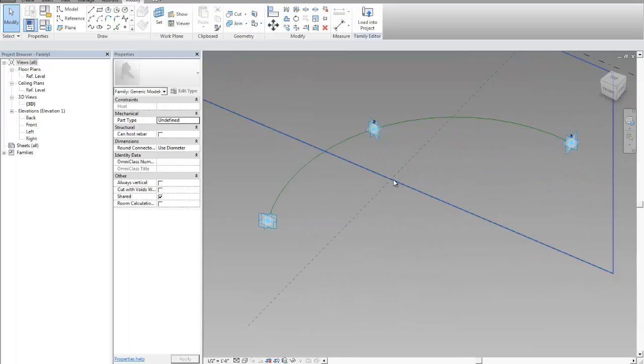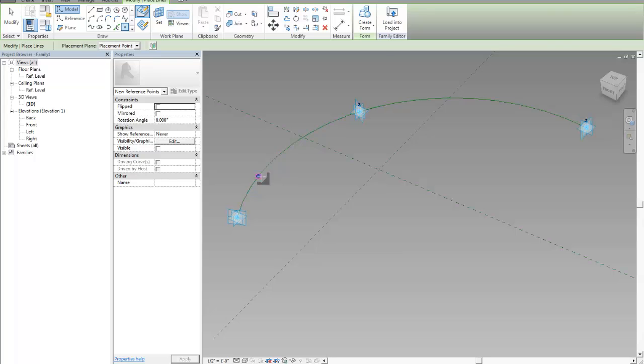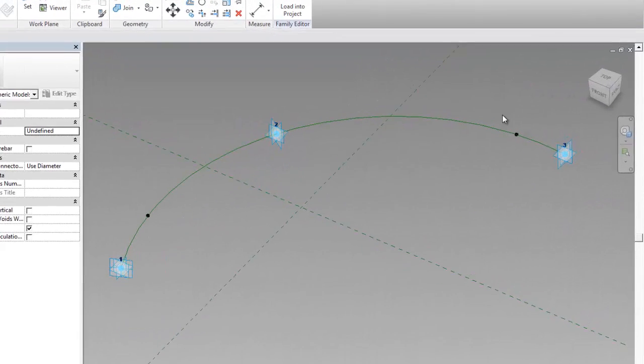Now in order to create an extrusion like a tube, give it a radius and give a radius to that tube, we want to drop a point, and I'm actually going to drop 2 just to make sure, because sometimes Revit tends to freak out a little bit. So I'm actually going to do a sweep between 2 profiles versus a sweep on just one profile, like an extrusion on path. I'm going to do a sweep blend.